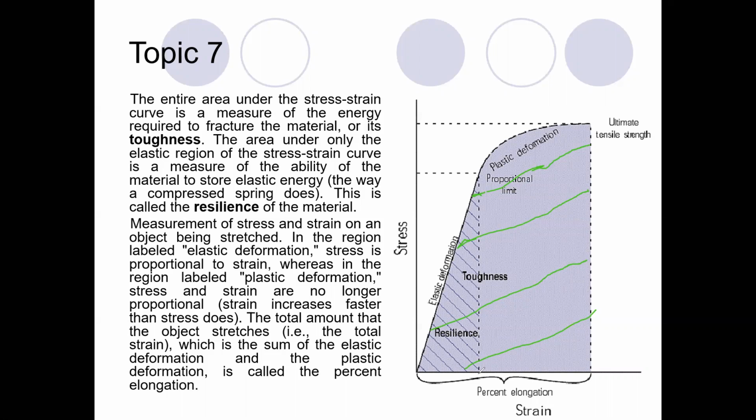And that part here is a triangle. It is elastic energy, called resilience. So here is energy that exists only in the elastic part of the deformation. And we can compare it, and for plastic deformation, as usual, you must apply more energy.